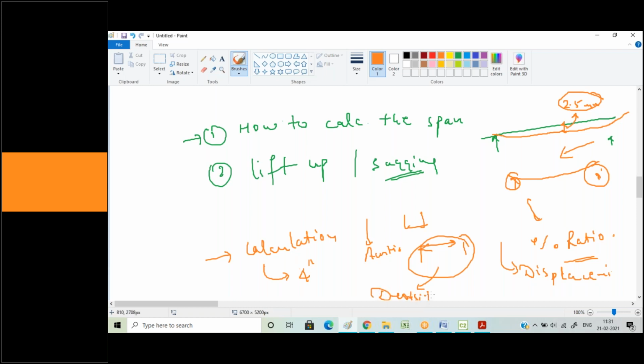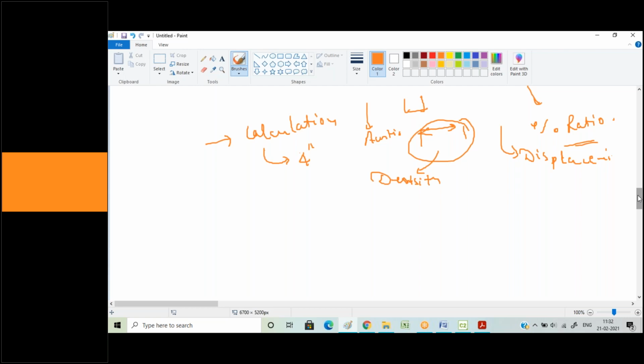Because say if you are using a denser medium compared to water, say crude, which is a very heavy fuel, your span basically decreases. When you're using crude, your span will decrease because you have to support your pipe much closer compared to the supports you were using for pipes carrying fluid of a comparable density to water. So that is the case over here.